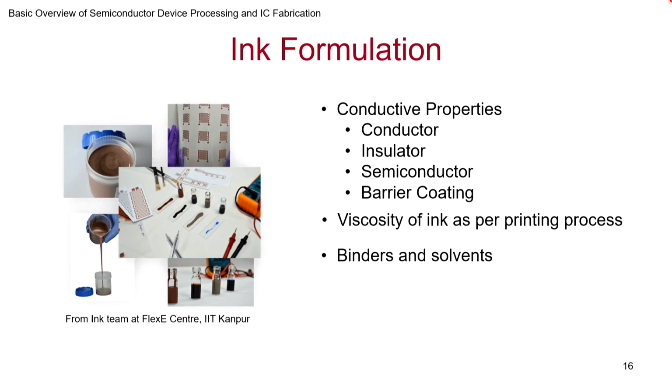Then you also need to add binders as well as solvents, so that they spread out and they bind to the surfaces that you want them to bind. A lot of chemistry is involved here. And then you sometimes put in additives to make sure that they smoothen out, they dissolve better, and so on, so the thin film properties improve. So you can actually play with the ink, and there's a lot of research that goes on. And then, of course, finally you compare it with regular devices once they are done.